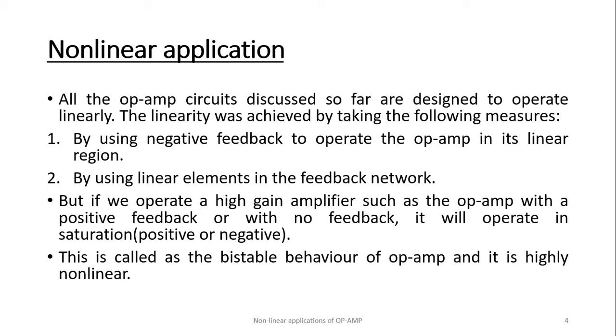Means if we use negative feedback, it creates linearity, but if we use positive feedback or no feedback, then it will operate in positive saturation or negative saturation. The voltage comparator and the Schmitt trigger circuit using op-amps operate on this principle.